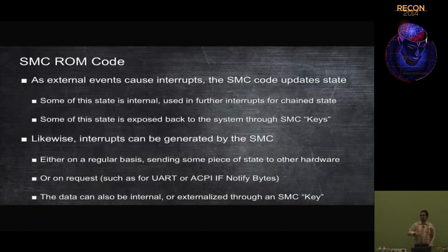It can also generate its own interrupts. So it can receive interrupts, and it can generate interrupts on the bus, and these interrupts are then captured by the driver that runs in the OS, and the driver will then take action based on those interrupts. So for example, when the SMC chip senses that there's a drop because the accelerometer sends it the information that there is a sudden change in G-forces, it'll send an interrupt to the OS driver, which will then talk to the SATA driver or the HCI driver to spin off your disk so that it won't get damaged by the time it falls down. So they've got a two-way communication between the two.